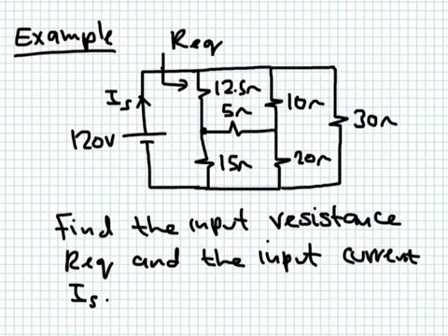So in order to simplify this circuit, we can use the Y to delta. So you can see here these 3 resistances, they are all connected to this central point. So this looks like a Y connection. Okay, so you can define the points. These nodes, give them A, B, and C, and then connect them with resistors, and then try to find these equivalent resistors. So we're now going to use a Y to delta connection in the hope that you can break this circuit into series and parallel connections. So let's see how this is done.